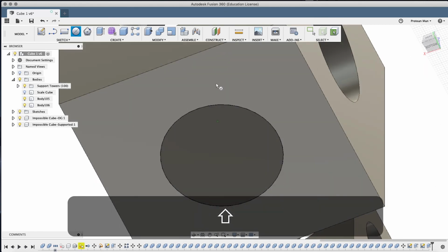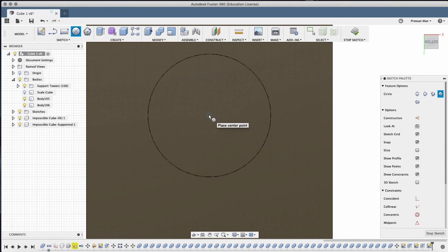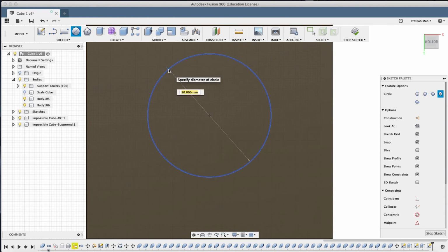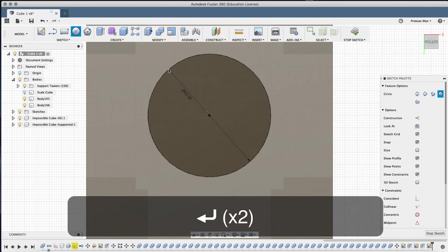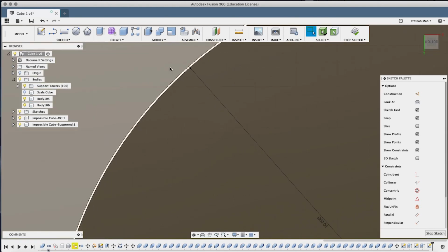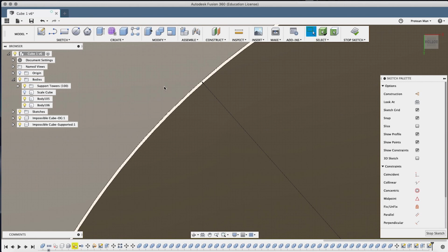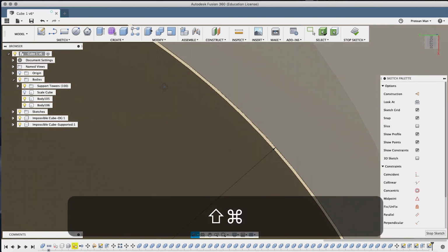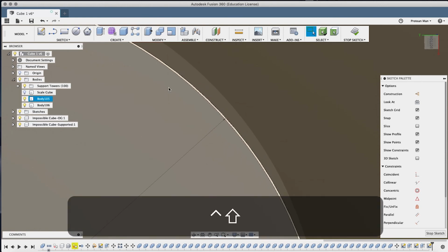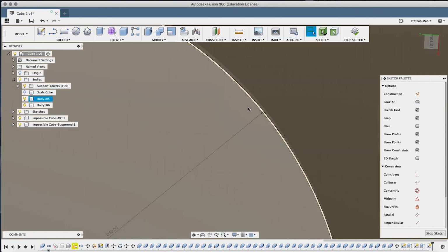Go to the center and draw all the way to the edge, 50 millimeters. Hit enter. Hit enter again. Now here's where you get to practice your zoom in and your other sort of fine tuning. And you're going to use one new thing. If I hold shift and command, no, it's not that. What is it? If I hold control and shift while I drag the middle mouse button, this is a new movement command. This is fine tune zoom.